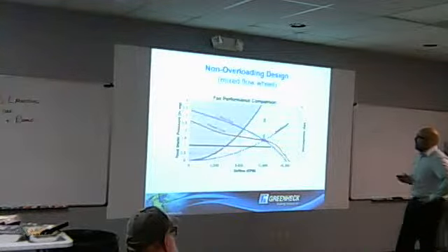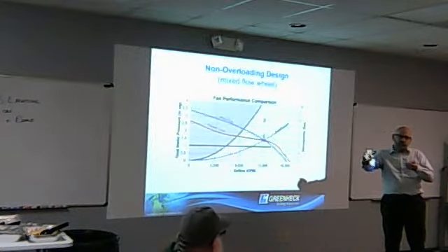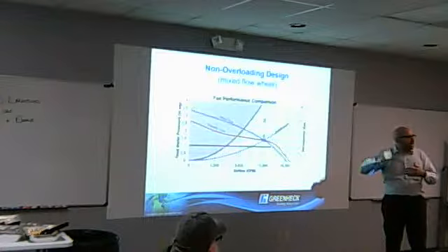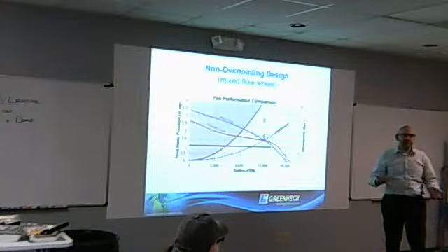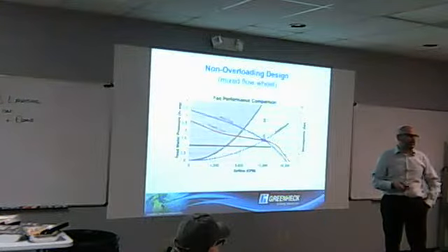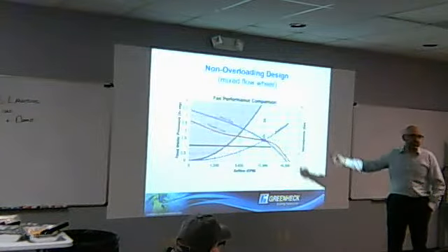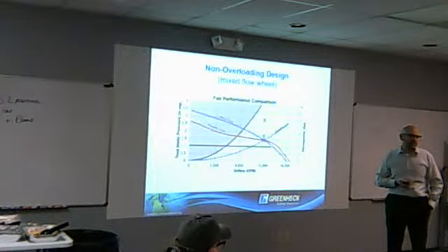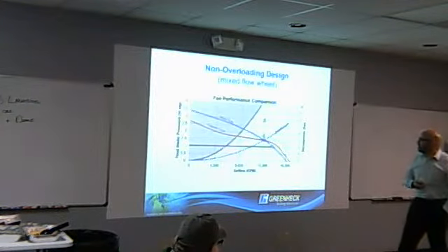You know the story. Another sidebar to this, like terminal units, we have a statement that says do not operate terminal unit without discharge ductwork. Most terminal units have little forward curve wheels. They start operating without ductwork, they overload it, they burn it out, and say, oh, I was just using it to circulate air or something. Best not to do that. Connect at least something to it. But if you've got a drive, you can program all your overloads in the drive usually too. Yeah, save it. Our units come standard with VFDs and drives because they're direct drive. On the little terminal box, it's just a little rheostat controller.